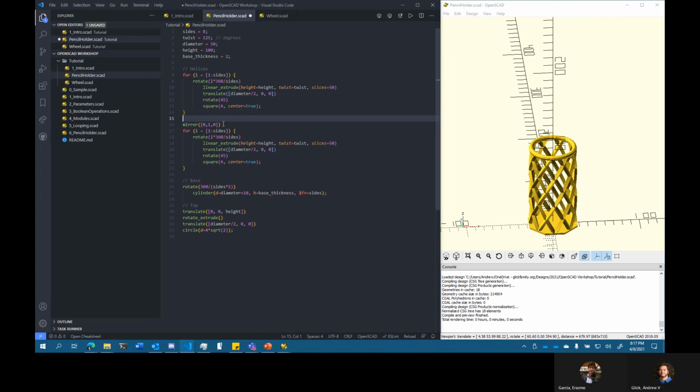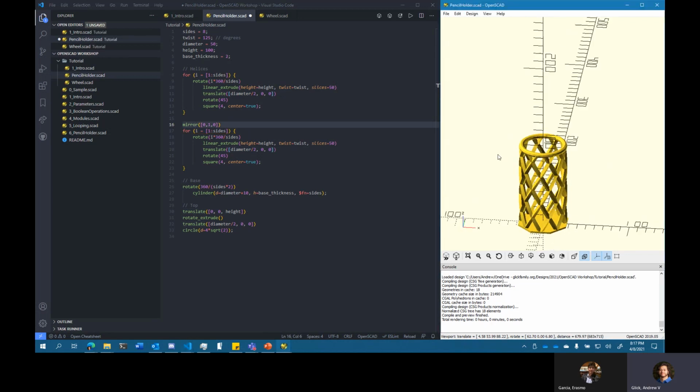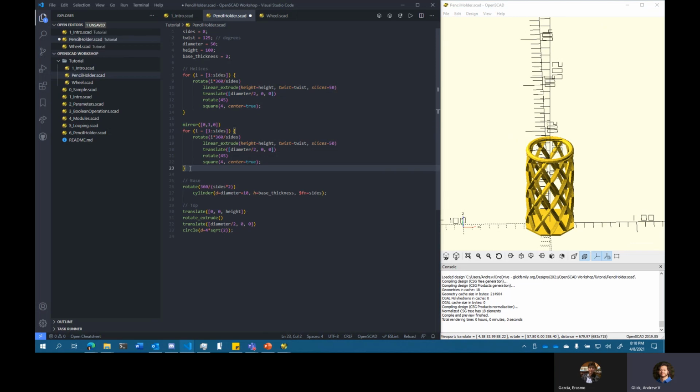Yeah. And just another thing that kind of confused me for a little while is, with mirror, why would I have to duplicate this? Because I just want to make a copy with the mirror. And that's just because mirror is like rotate or translate, or the other operations, in that it's just mirroring it. We don't necessarily want to copy it. So there's a mildly fancy duplicate mirror function that I wrote that allows you to apply a mirror and also have it duplicate at the same time. But perhaps topics for another workshop.